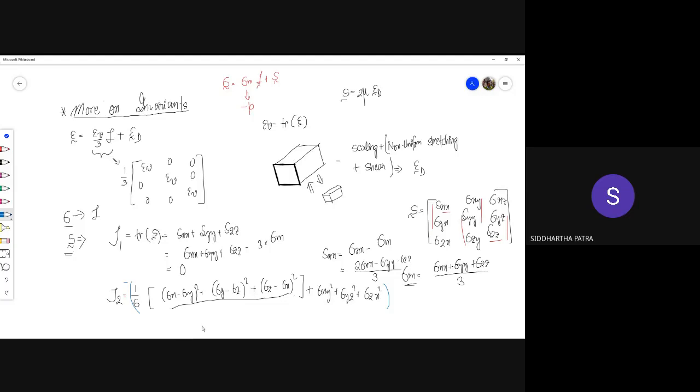Okay, so if it is turning out to be difficult, let me tell you that just like I2 for stress, there are other ways to represent I1, I2, I3. For example, you can do this. Just like I2 for stress, we know that for any arbitrary tensor, the second invariant is essentially trace of S whole squared, I hope you recall this representation, minus trace of S squared. So that would probably help you in simplifying the expression.